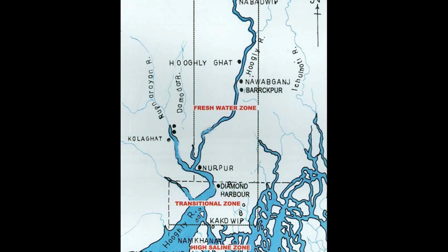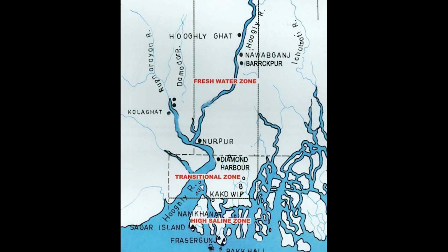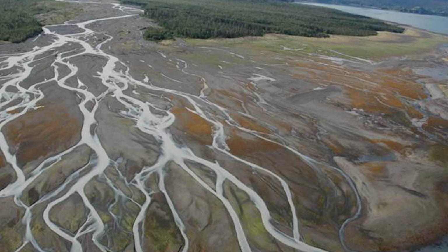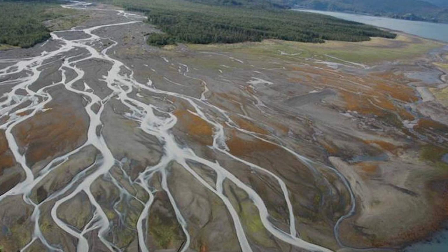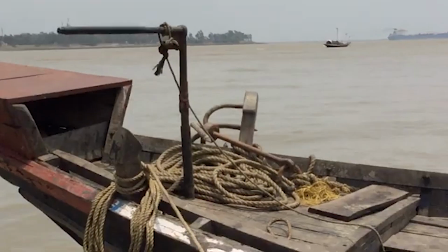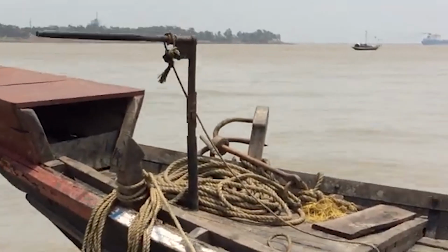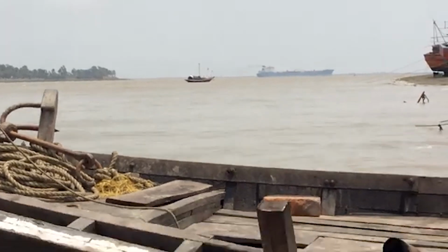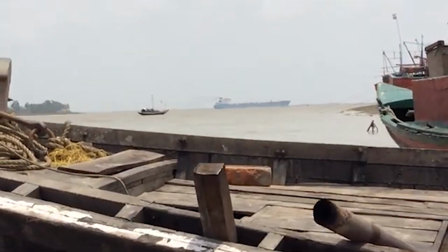Depending upon the topography of the area, the estuary stretch may be 50 km or even 300 km as per the river bed slope. For Hooghly River, which is in the eastern part of India, it stretches to about 175 km. However, the issue which bothers most is that during the tidal period, there is an ingress of saline water or salty water within the estuary, which we normally call saline water or salinity in river.